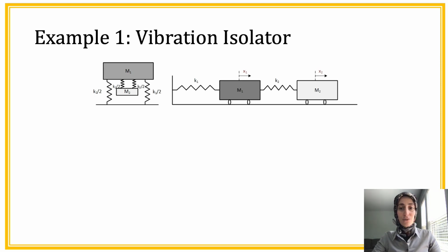Design a vibration isolator for a system having base excitation. Describe how the reduction on the primary mass is affected by the choice of different vibration isolator mass and spring constants, and visualize the force of single degree of freedom and 2 degree of freedom mechanical systems.